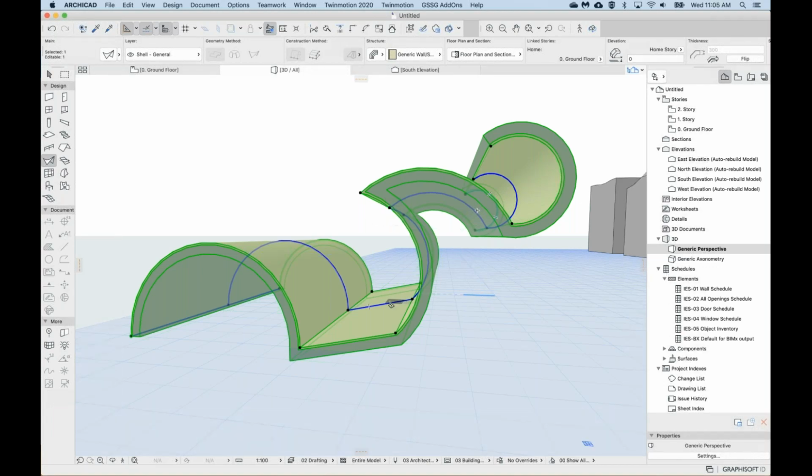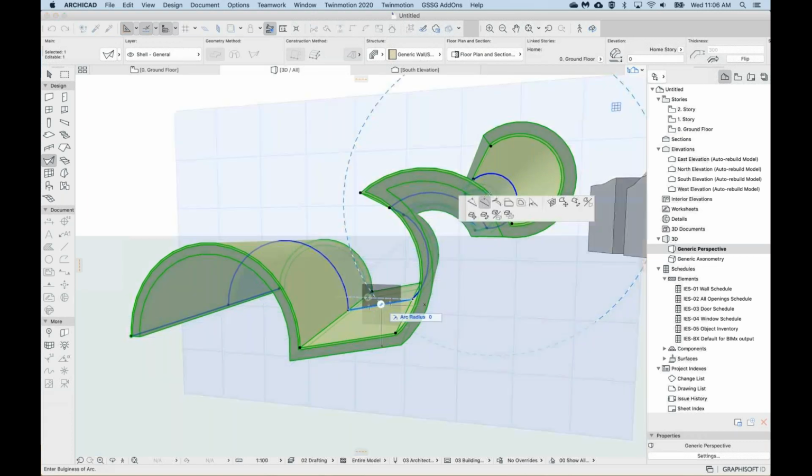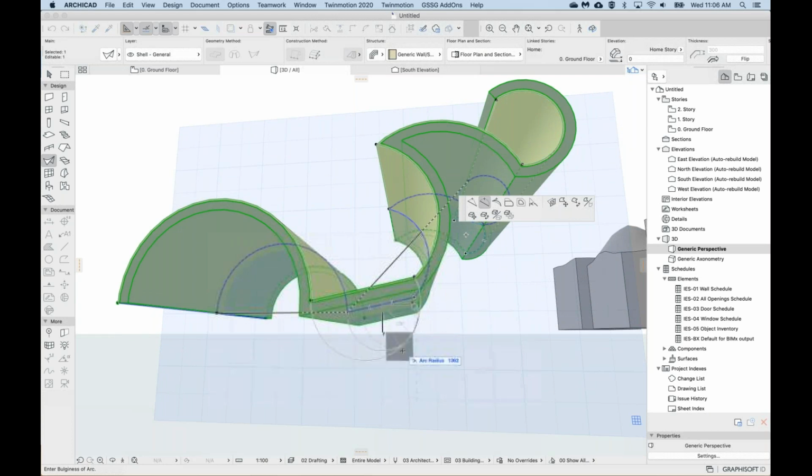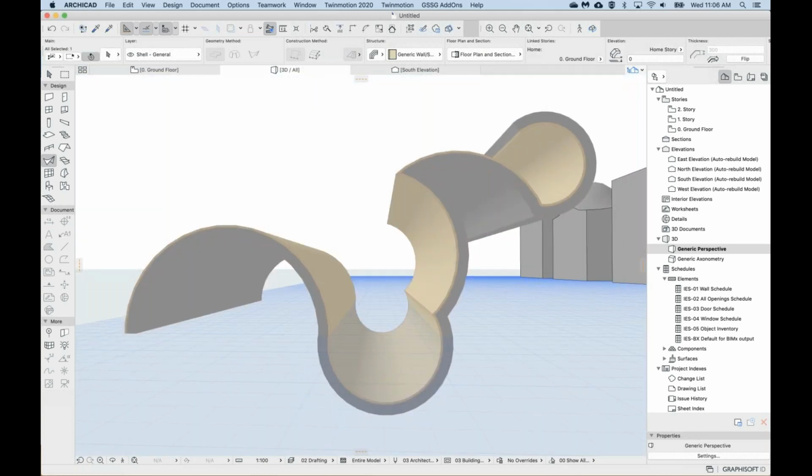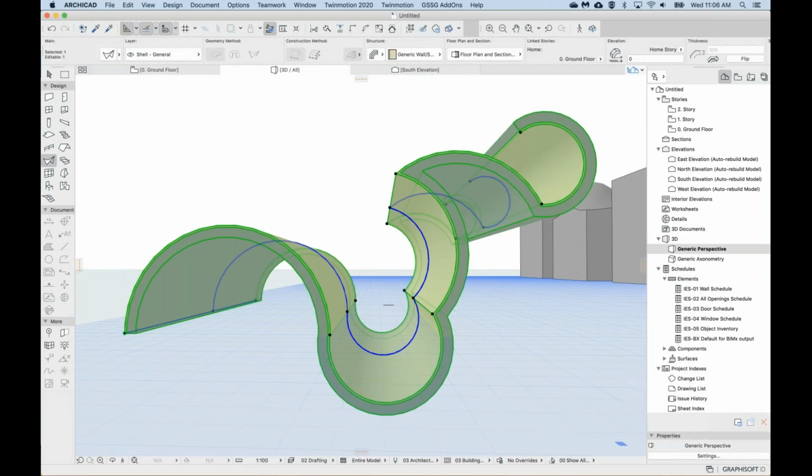Do you see the selected blue edge? So when you hover over the blue edges, then your cursor will turn to a bold Mercedes symbol. And when that happens, then click. So I can do the curve. I can't yet because it's finding the surface. So I just need to move my camera, then I can curve. Yeah, so we can only edit this blue line, which represents the profile, which is extruded.